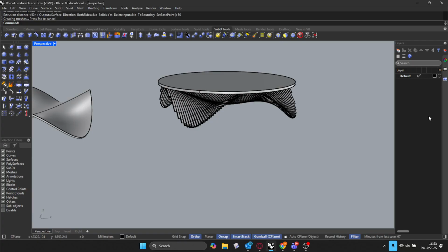You can add loops up here. Click on loop just there. Yeah, that one, insert edge loops. Select the middle edge, press enter, and now you can drag a new one to the right, and now you can play with that one.